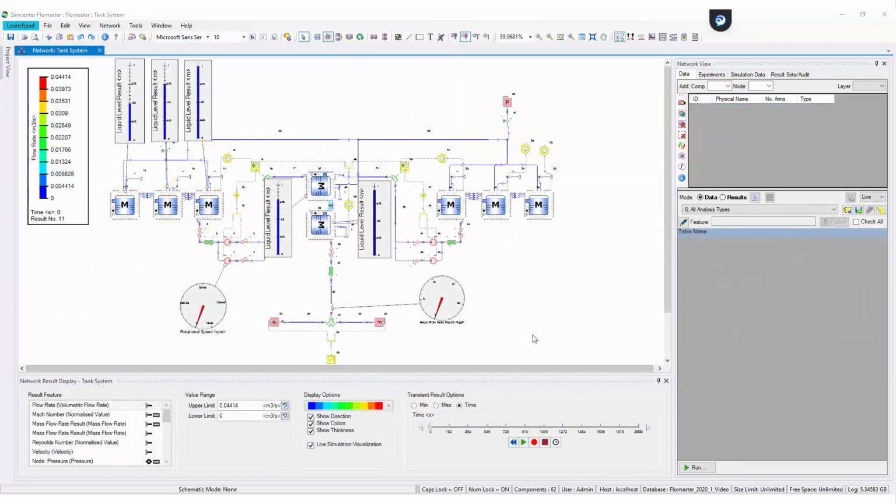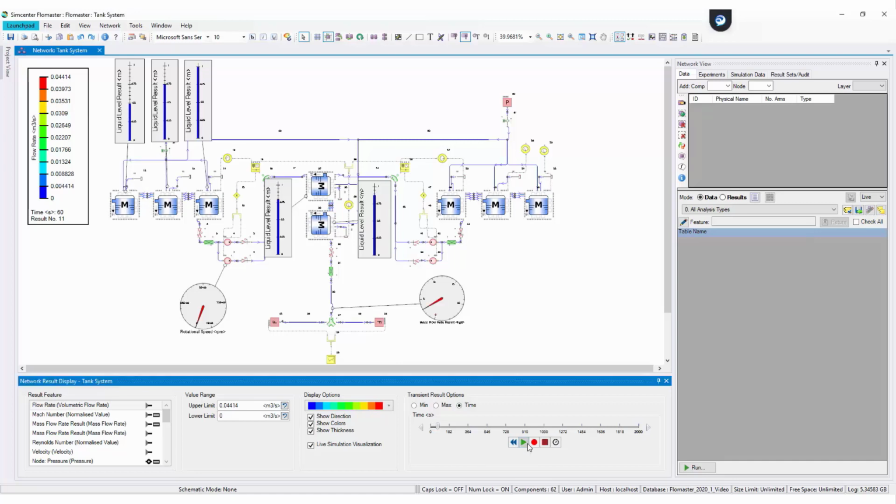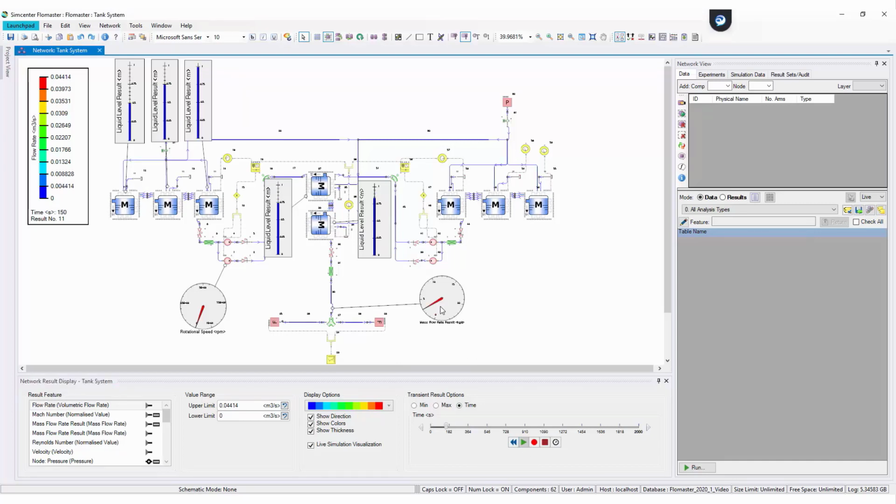In the second example, we're going to look at a storage system that has been pre-configured with sensors added. Storage tanks to the left and right of the model supply 2 receiver tanks in the center, which in turn are emptied by 2 consumers below. We've added a radial gauge to the pump and connected vertical linear meters to the storage tanks on the left of the model, and the 2 receiver tanks, which all show the level. We can also see the flow demand on the radial gauge.